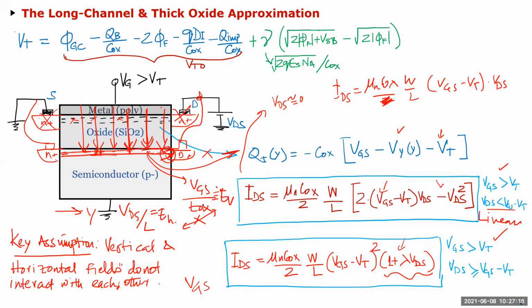Now you have 4 billion, B for billion devices inside it. That's because of this channel length shrinking and W also shrinking. At the same time, you want to make them faster. In order to make them faster, you want to make this TOX thinner as well. And that's where all the process challenges have gone into.